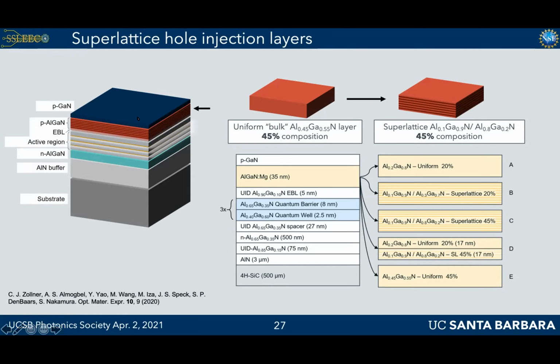I see. So you can't have like a P-AlGaN and AlGaN tunnel junction? In principle, you'd want to design one, and I'm sure there are tricks you can do that have to do with the polarization to get some sort of polarization-enhanced tunnel junction, and that's what everyone's working towards. But for now, all the results I've seen have relied on some sort of P-GaN. It's pretty thin, so it's unclear how huge of a light extraction penalty it is. But as of right now, no one's quite been able to get rid of that P-GaN yet. Fair enough. Thank you. Yeah, thanks.